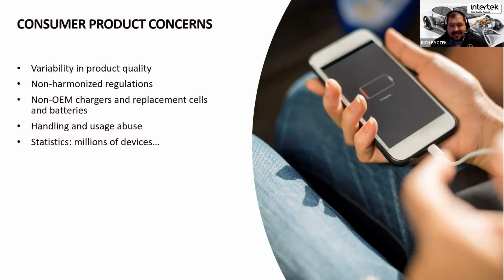When you go to buy the replacement charger, that exact replacement charger costs you $35, $40, but you see one that looks the same at the store for $1 at the register, so you pick that one up. That's a potential stress source because the controls may or may not be good enough to prevent that temperature, current, or voltage range from being exceeded in the battery. We expect that there is some level of protection within the batteries, but the more likely you are to present a stress source, present an abuse condition, present something outside of the normal handling ranges, the higher the likelihood that that's going to make its way into the battery and cause an issue.